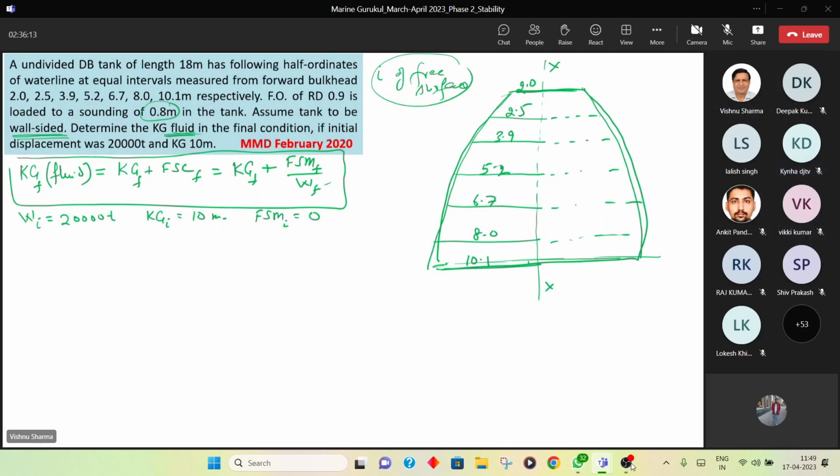No, the answer I expected was that for I it will be a case of vertical ordinates, and for vertical ordinates it is important that all ordinates terminate at one axis, and the formulae are based on that. Correct? Yes, sir. That is the logic you should have given. That is why we are taking half ordinates. Yes, the ordinates are terminating at x. So we'll work around with half. Now please make the table with half ordinates.